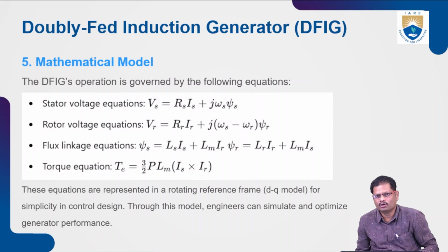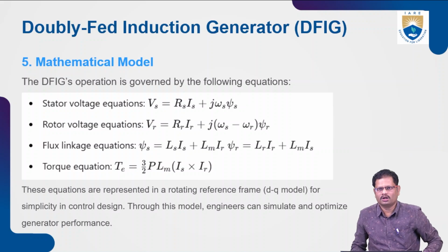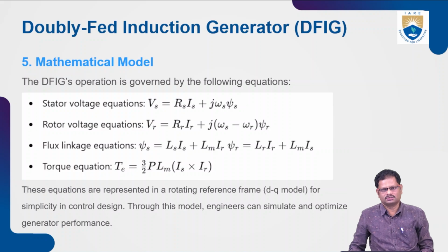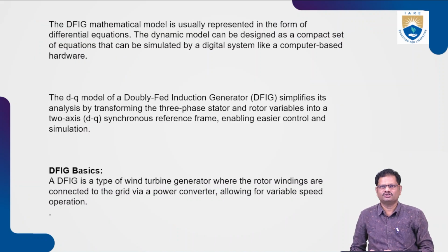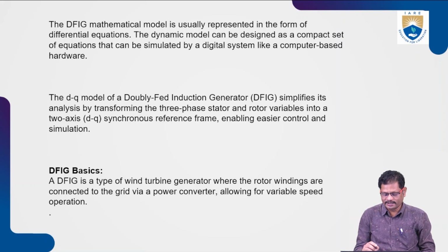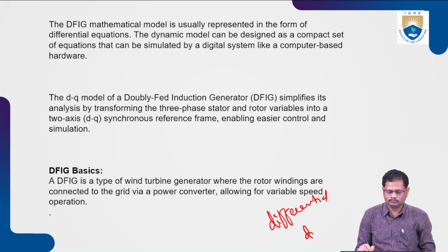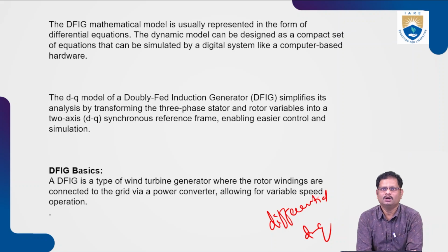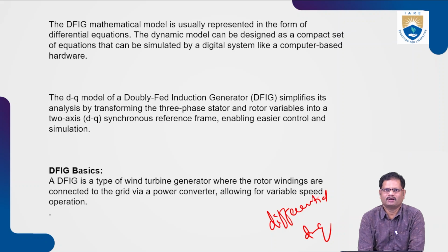So it's a mathematical model. This mathematical model is used to simulate and optimize the generator performance. The DFIG model is usually represented in the form of differential equations and also in the DQ reference frame. The dynamic model can be designed as a compact set of equations and can be simulated by a digital system like computer-based hardware.